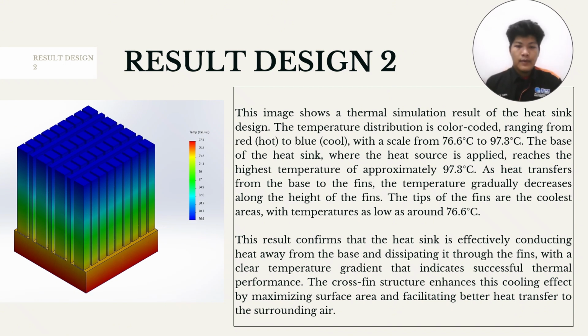This result confirms that the heat sink is effectively conducting heat away from the base and dissipating it through the fins, with a clear temperature gradient that indicates successful thermal performance. The cross-fin structure enhances this cooling effect by maximizing surface area and facilitating better heat transfer to the surrounding air. Thank you.